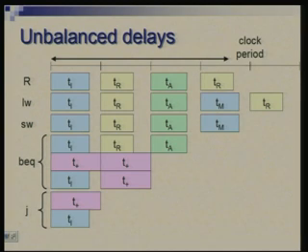So now the clock will be dictated by this time, and we will still follow the same approach: R instructions take 4 cycles, LW 5 cycles, SW 4, BEQ 3 and J a single cycle. But now notice that the clock period is larger, and it has to be sufficient to accommodate any of these individual activities.